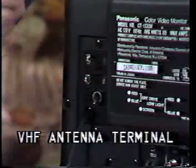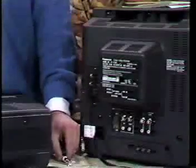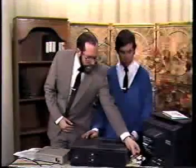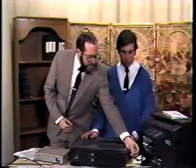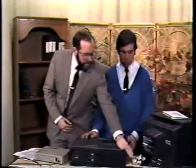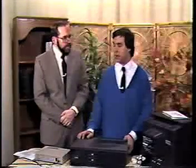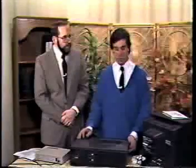On this particular set, it's this set of screw terminals here, and so I'll need this matching transformer, which if you're a cable customer, you should already have, and I would screw it on here, which will give me the cable connection. Okay, now some TV sets also have this connector down here, which is the 75 ohm input. And we could bypass the matching transformer and plug our jumper cable directly into there, could we not? Right, John. Again, it depends on exactly how your television set is set up. Some of them will say cable in and will already have that terminal on without having to put on a matching transformer.